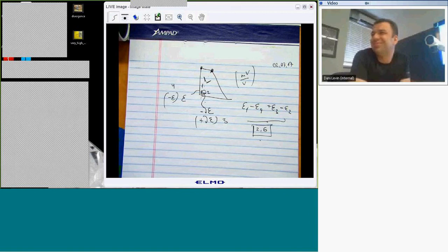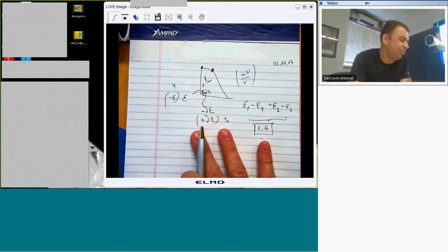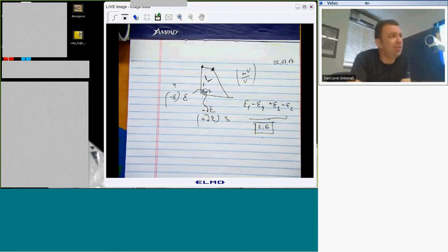But in transonic conditions, if you disturb the flow, you might create a shock or move the shock from where it was without the instrumentation to some other place, and that could be an issue. All kinds of difficulties. So it's robustness, ruggedness and survivability on the one hand, and on the other hand, you don't want to disturb the flow, particularly in higher speed flows, which are more sensitive. So in this case, the shielding will be much better in transonic or supersonic flow.